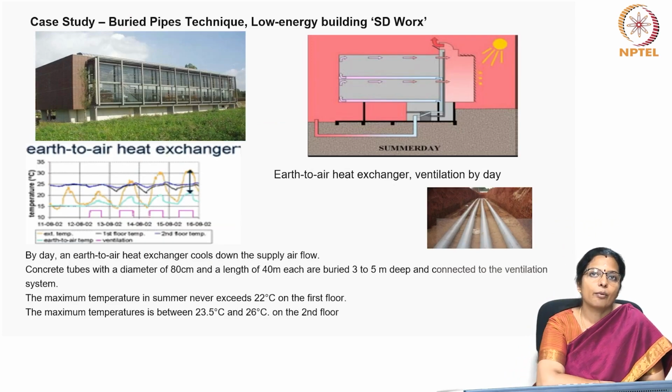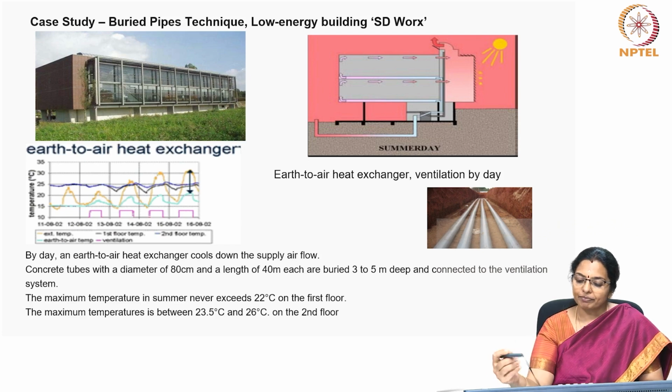Another case study of buried pipes techniques or earth air tunnels is the low energy building at SD Works. So SD Works uses the earth to air heat exchanger, which has pipes running at about 3 to 5 meter depth.